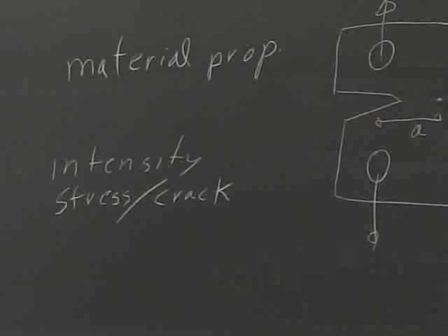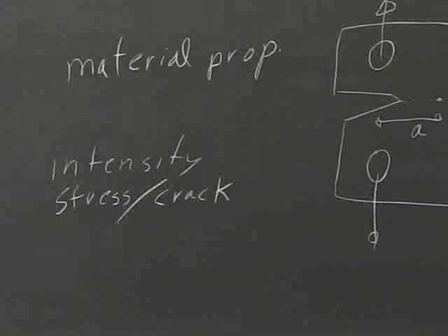So if I'm having a load here, and I'll put it as a stress sigma, that's going like this, for crack growth, it's not going to result as much as if it's doing like this. Well, it's not the same frequency here, but per cycle, the fact that you're going down further is crushing back your metal in the plastic zone. So when you do it again, you can get a greater step per cycle.